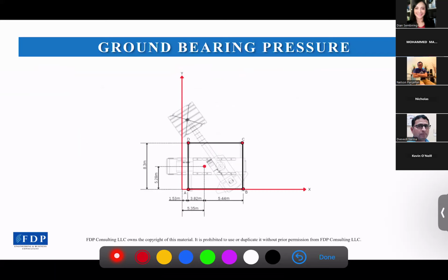But don't forget, you need to be consistent with the origin point. So all your COGs should be measured from the origin point that you have decided at the beginning. You are free to choose wherever you put the origin point as long as you are consistent with using that in your calculation.